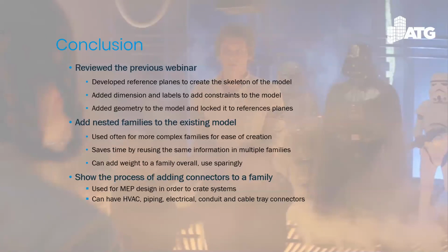In this instance, I used nested families to create the different heads for the R2 unit, and then created some types based on those. I also used nested families just for more data type information when I added the data recorder type information in. I use that quite often on families. It is not for the geometry, but more for the data.